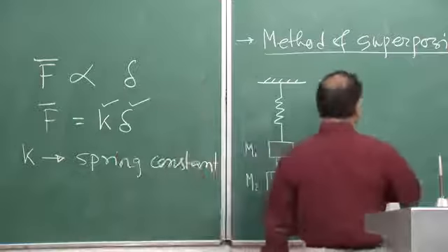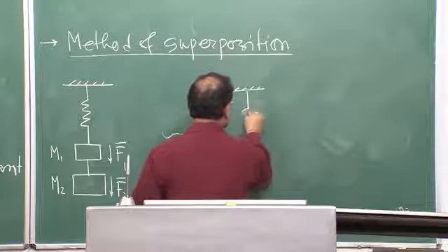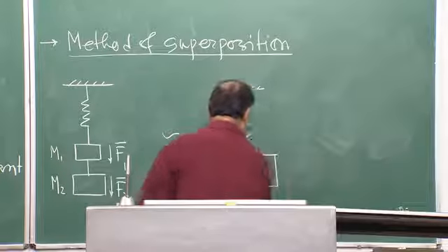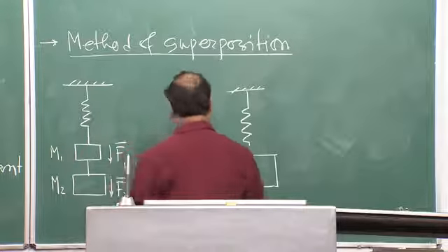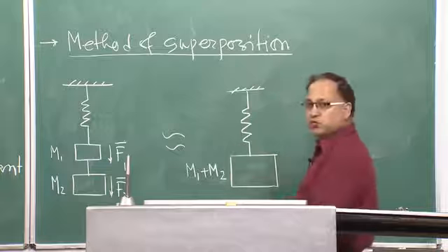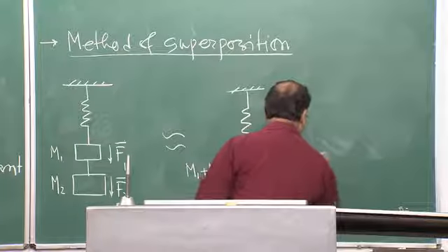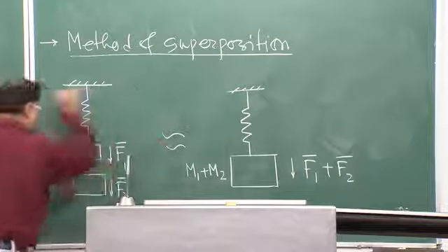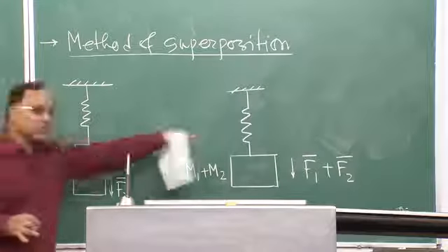Now this is equivalent to another system made of the same spring where I am applying a single mass, which is nothing but M1 plus M2, the summation of these two individual masses, and which is causing a force F1 plus F2. Now whatever response you get from this system, the same response you will get from the other system also.